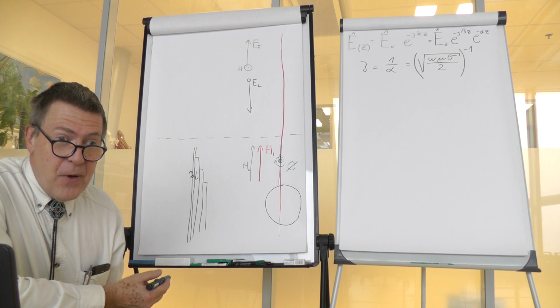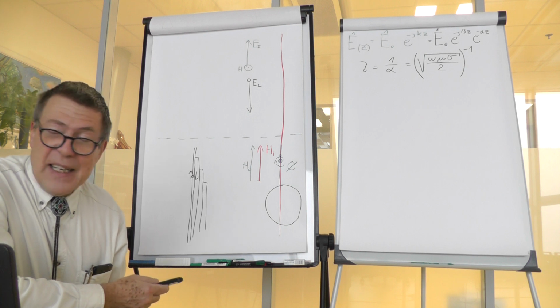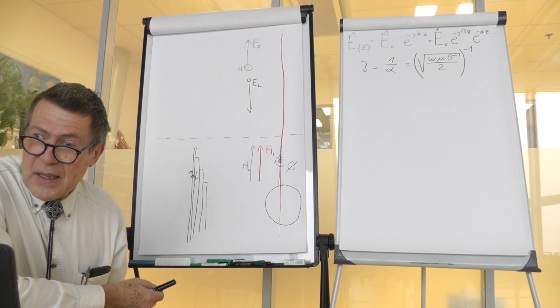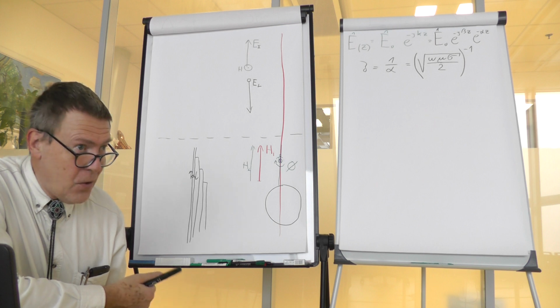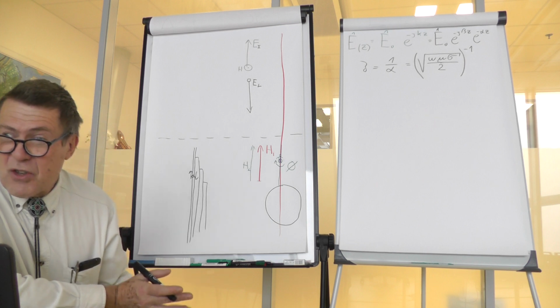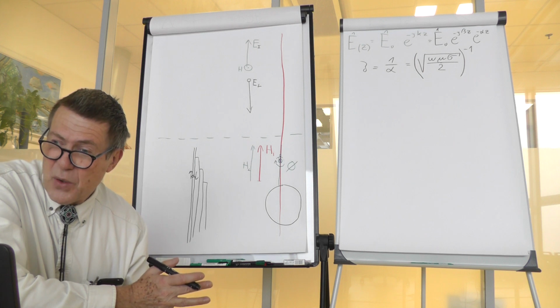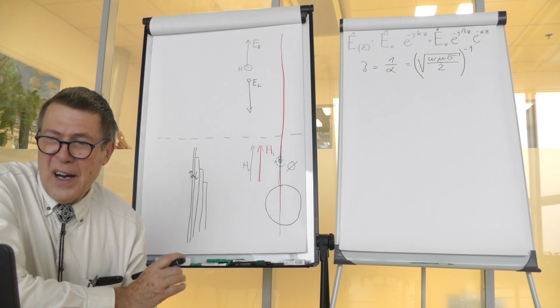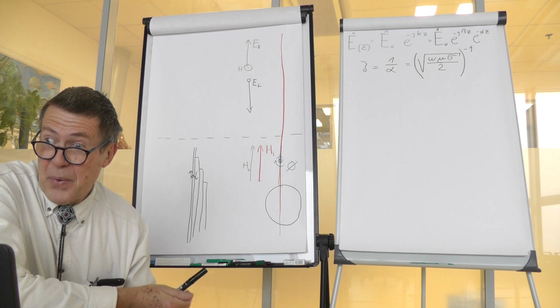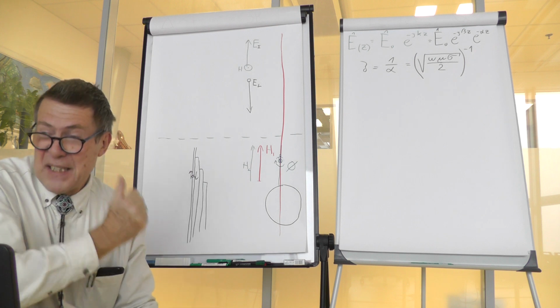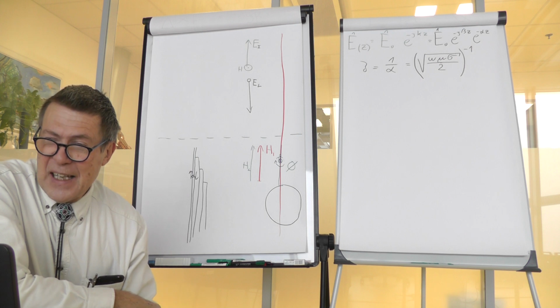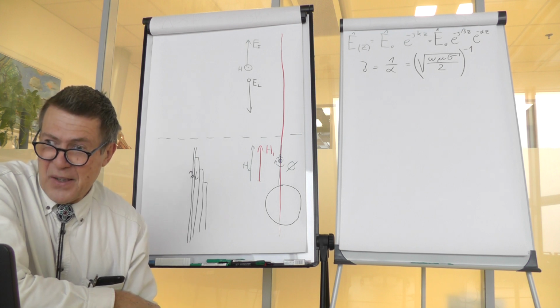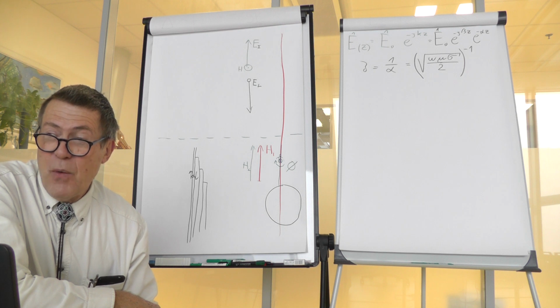if you have to design a transmission line for currents for public transport of energy, 50 Hertz, let's say, in Europe, then for low currents there is a rule of thumb. And the rule of thumb says you can get 4 amperes per square millimeter into a wire which is not cooled well.